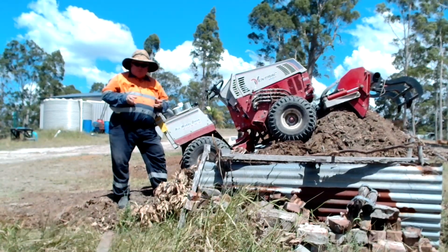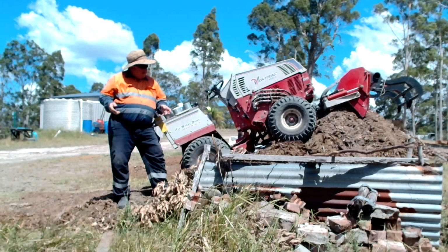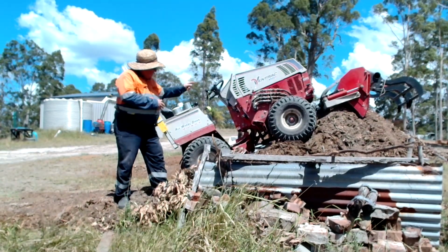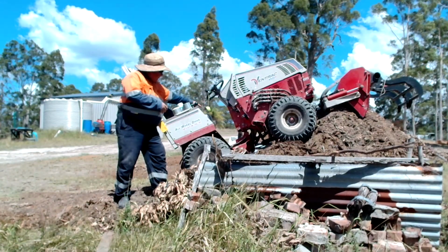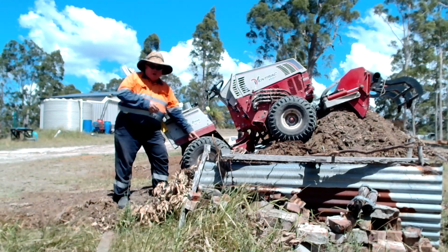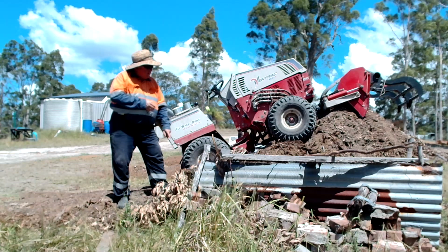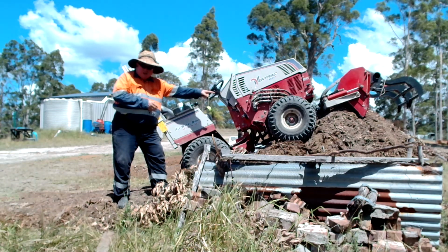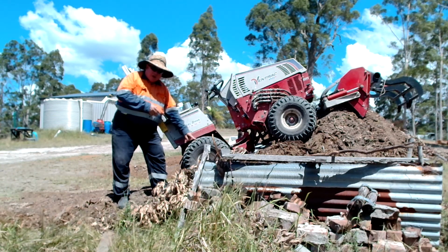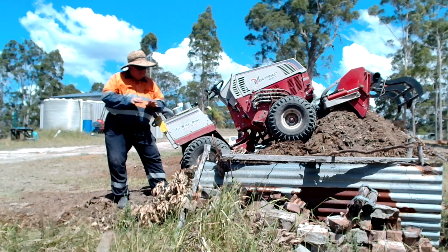So grades are important. On paper, they might look all right, but sometimes in reality, it's a very different picture. Look at the plumb bob again, way back. And what that's indicating is there's a lot more load back here. Granted, the bucket is empty. Normally that axle would be the most heavily loaded one, but right now it's here. My traction and braking is back here, but my park brake is there.